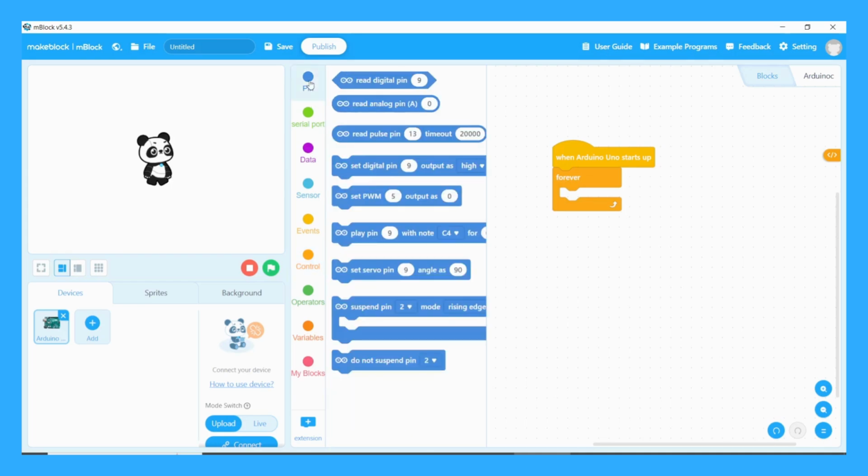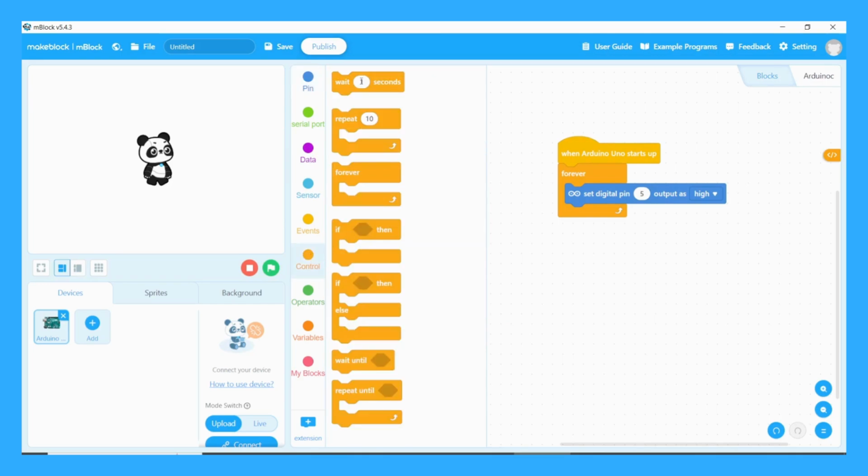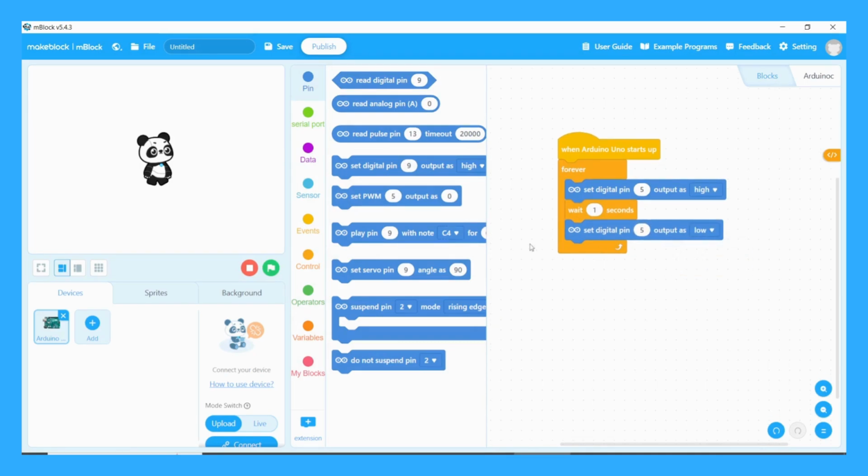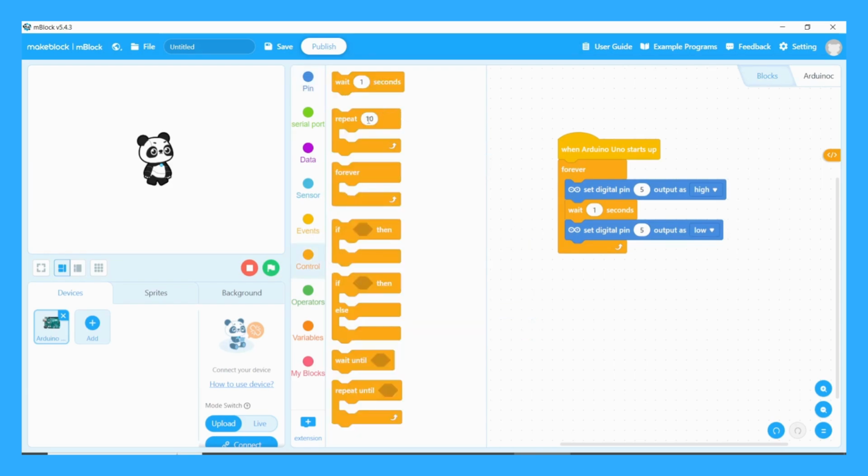First of all, we need to make the pin that our LED is connected to high. So we will give 5 volt DC to the LED from this pin and the LED will work. Then wait 1 second. Now let's make the pin low and turn off the LED. Then wait 1 second. That's it. The final version of our program will be as follows.